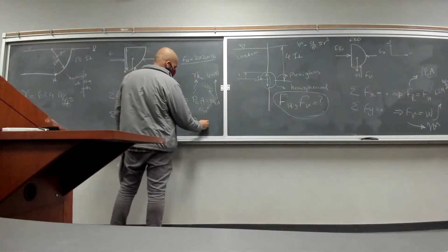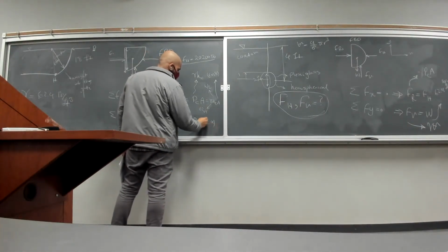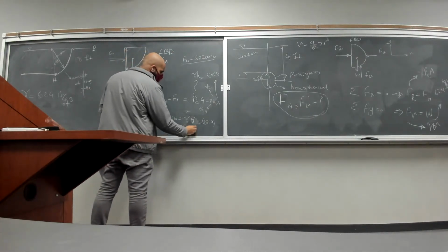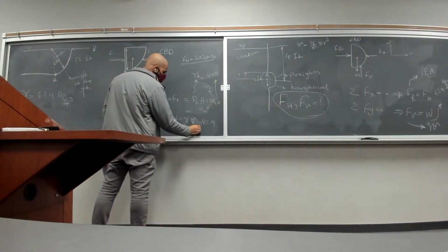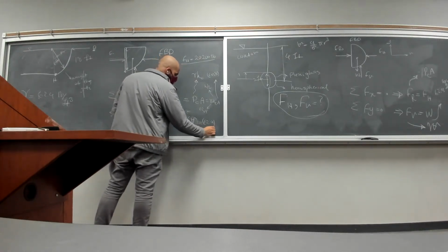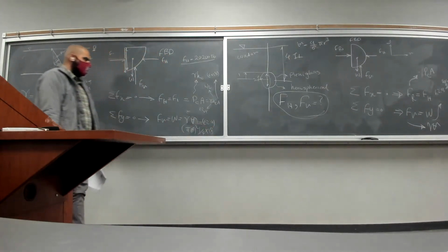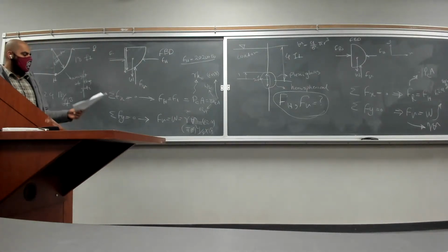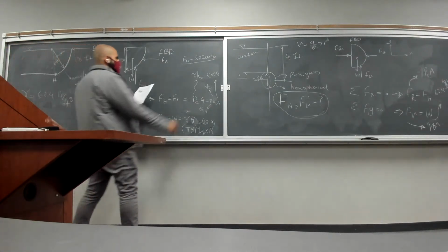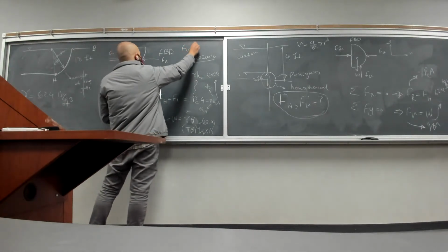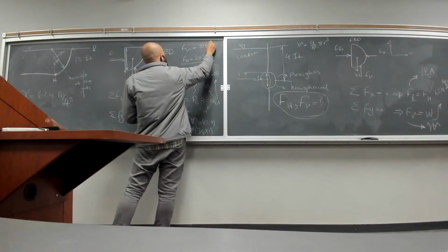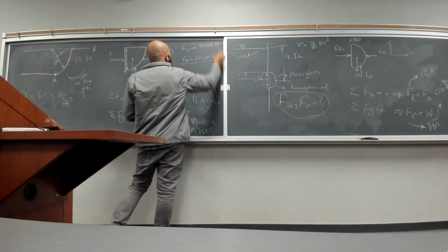So we're going to get 62.4 multiplied by pi r squared, where r is 6 feet, divided by 4, multiplied by 18. If you do this calculation, your F of V is going to be 31,800 pounds.